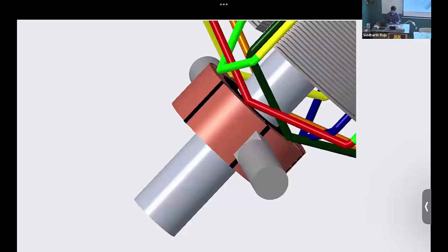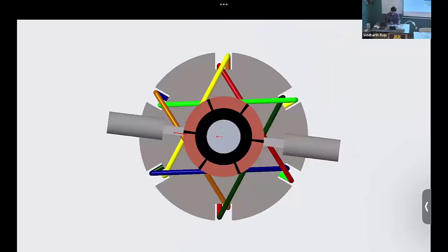So this is a rotor structure, and then each of those loops that we created would have its contact with the commutator. So that's what you have seen. You have seen a hook to which the wire goes around. So this is where your copper brush, the graphite brush, makes contact with the copper commutator segments that we have. And this whole thing, so this is where the contacts are made. Right? And as this rotates, it keeps contact.